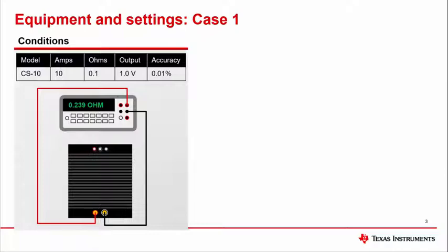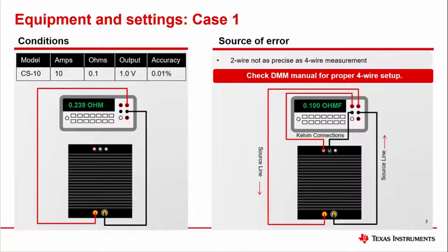Two-wire measurements are typically used for resistors with a resistance value much larger than standard test leads. As resistance measurements inject current to detect a voltage, voltages can develop across the series resistance of the test leads, which will contribute more error as the shunt resistance becomes smaller and closer to the resistance of the test leads. Therefore, you need to use a four-wire measurement to avoid this error.